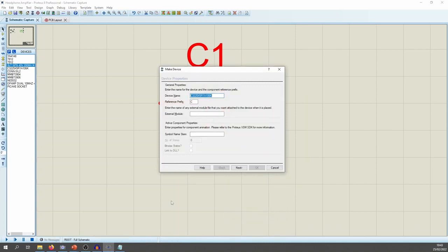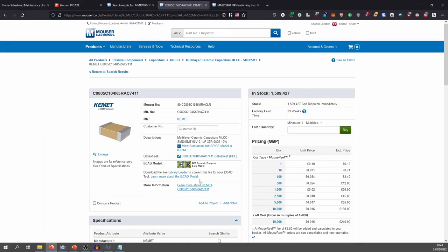So the way that you do capacitors and the way you do resistors and all these other devices, where you don't have the part number at the end of this search, you don't need the part number in here. What do we need to know about the cap? We need to know that it's cap. We need to know that it's ceramic. We need to know its value. Oh, this is another point as well. Because you can't do full stops in this particular box, if you wanted to do 10.3 nanofarads, you put the NF where the point would be. Yes, exactly. So this one's 100 nanofarads. It's 50 volt. Is it 50 volts? Yeah.